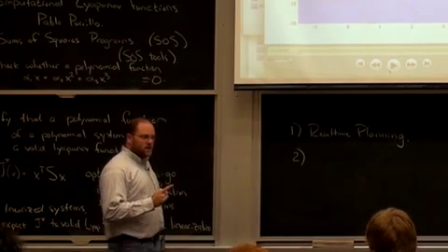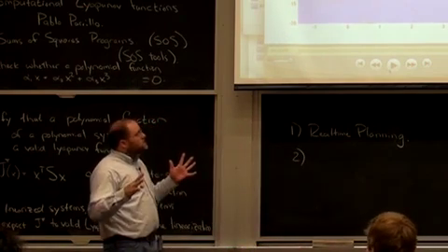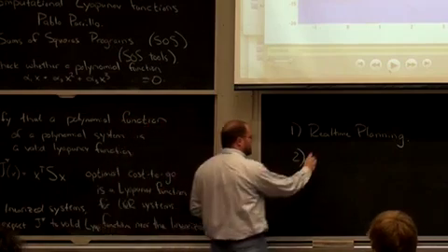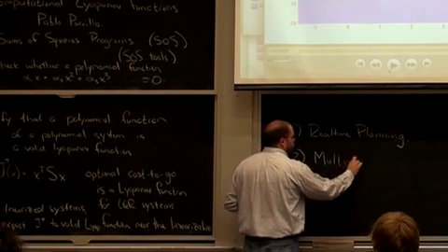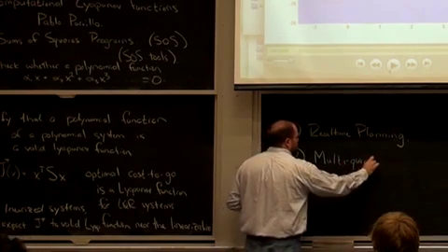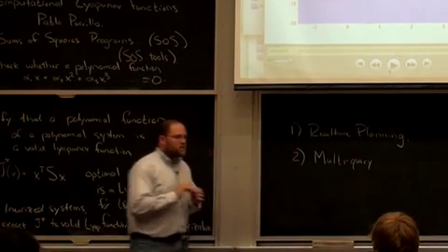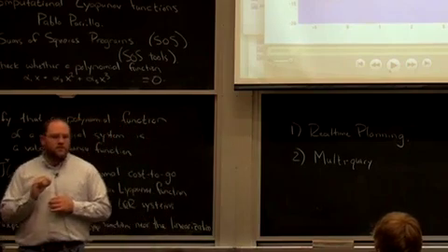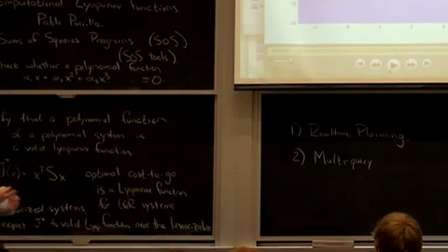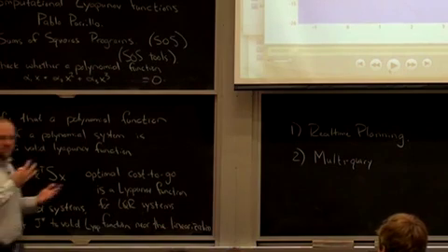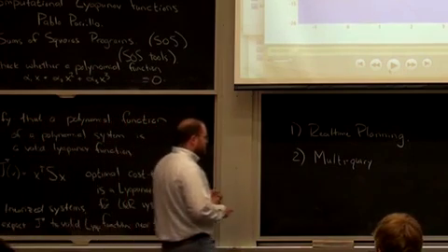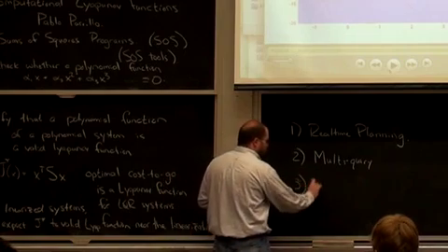The second idea was building these trees and doing multi-query, keeping your tree around and just finding your way to the closest point of the tree every time you execute. And that has the nice feature that every time I execute, my tree gets a little bit bigger and I know a little bit more about my robot. Yeah? And the last one was this feedback motion planning,